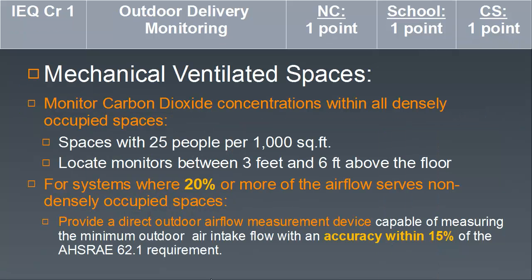The requirement for mechanically ventilated spaces is to monitor carbon dioxide concentrations within all densely occupied spaces. This is considered to be spaces with 25 people per 1,000 square feet. Locate monitors between 3 and 6 feet above the floor. This is considered your breathing zone.